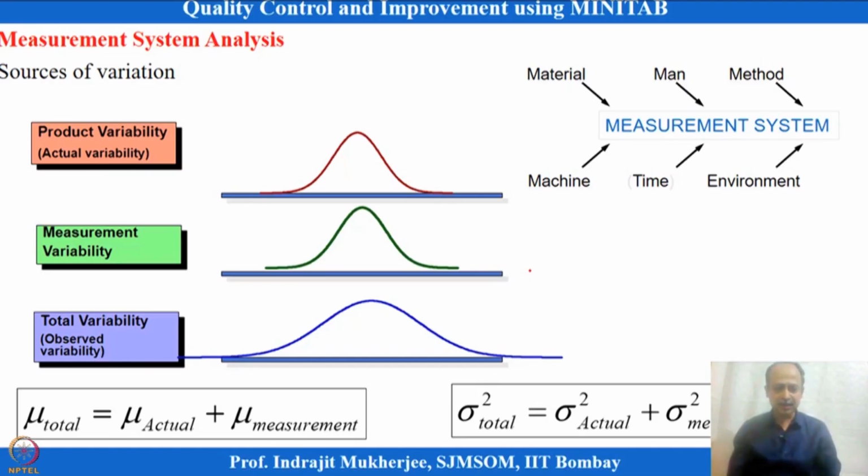So measurement of this bias can be in different ways. One is known as basic bias, that is what is the average observation and how far it is from the reference point. Okay, when I have only one reference information, one part, one instrument and one reference, that I am measuring several times and we get the bias information like that.